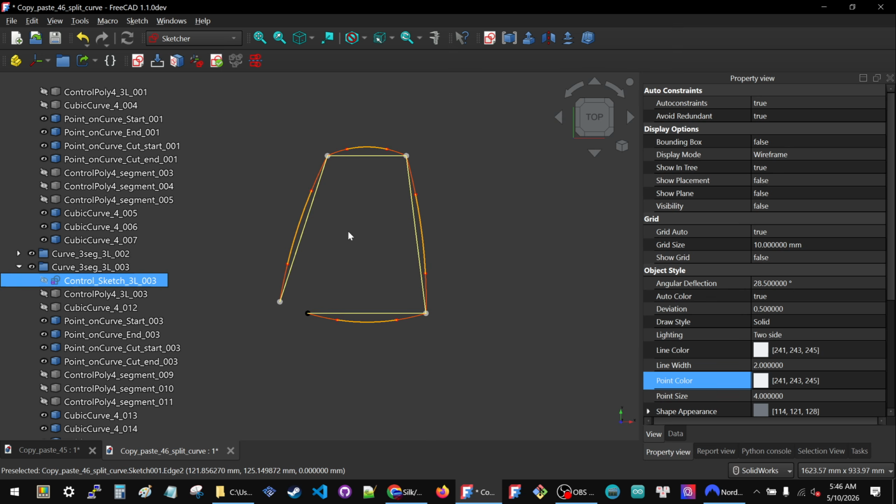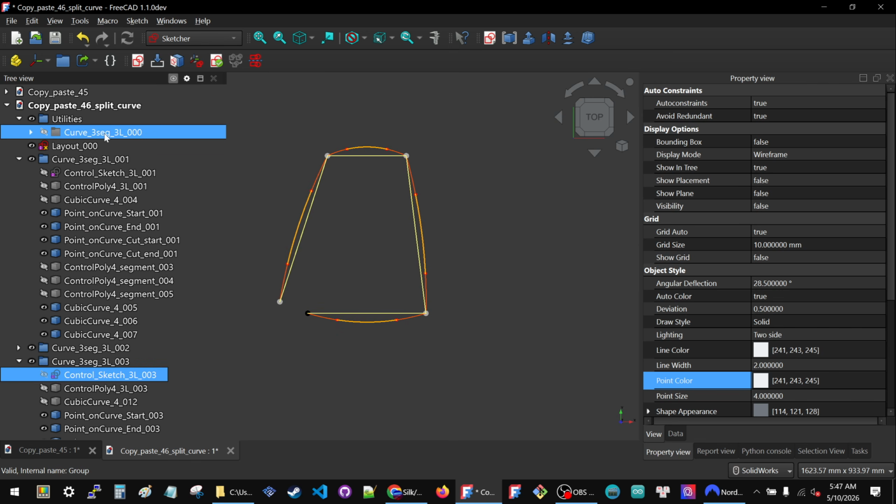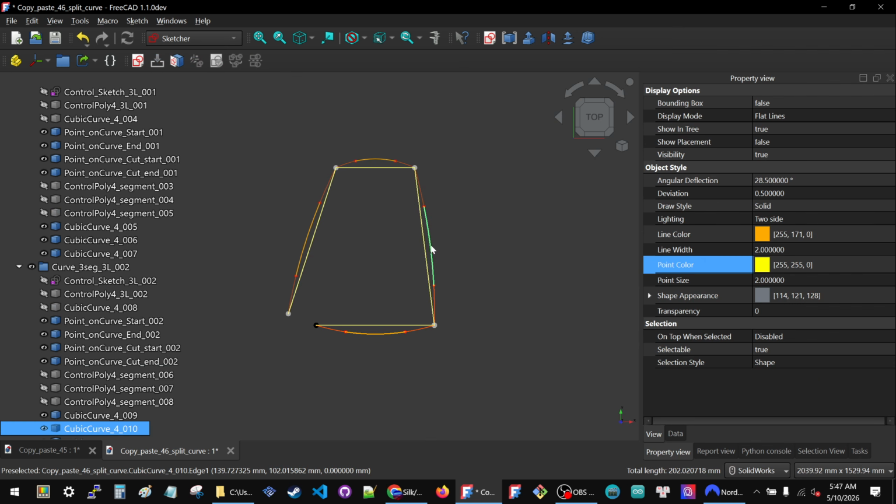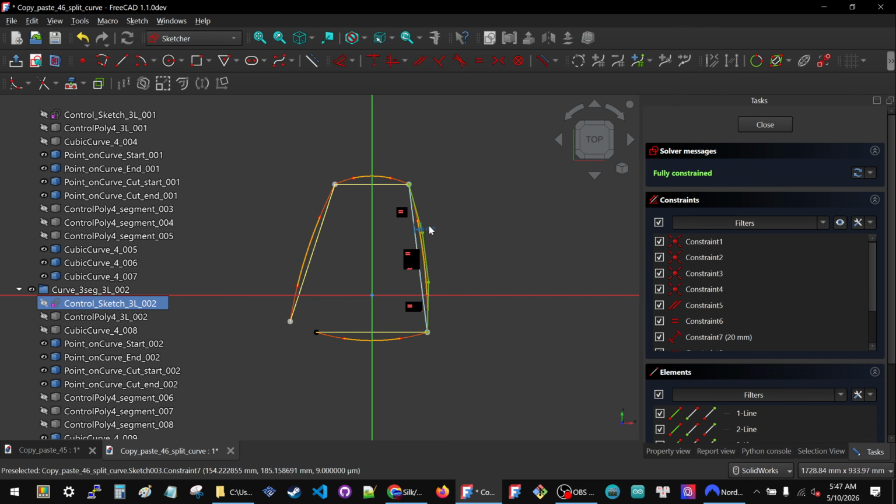Close it. And since I did that, based on the size of the sketch, now I think I also want the distance here to be 30 on these two as well. And there was nothing wrong with having it what we had in the original, but now that we have an actual layout, we can make these dimensions more meaningful. So I'm going to select this one. It opens the folder. Edit the sketch. Make this 30.